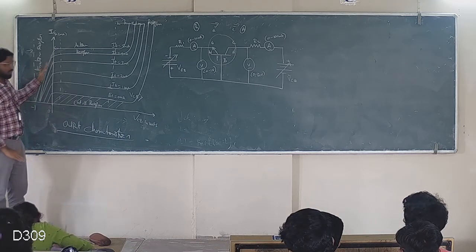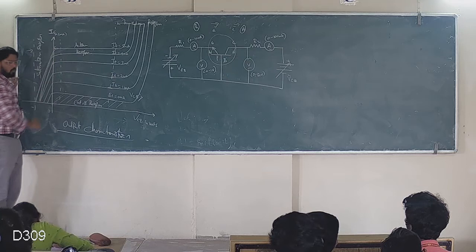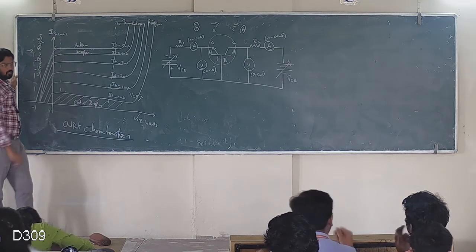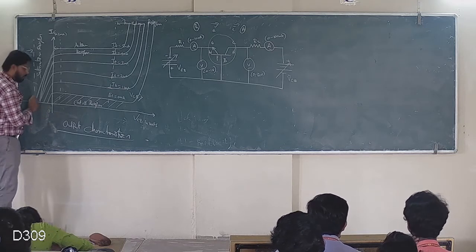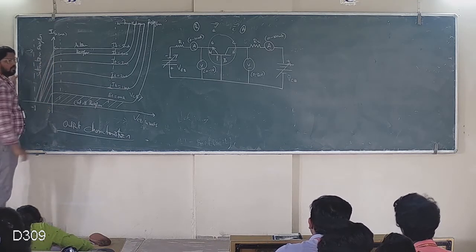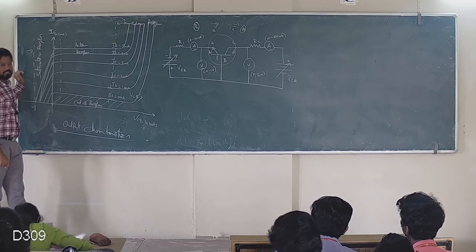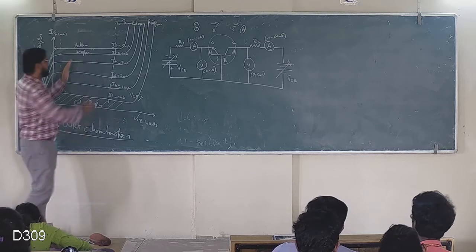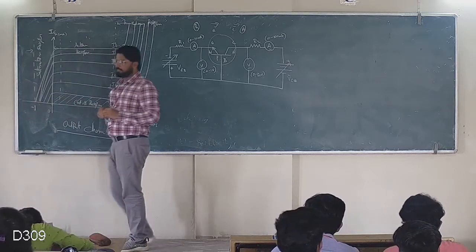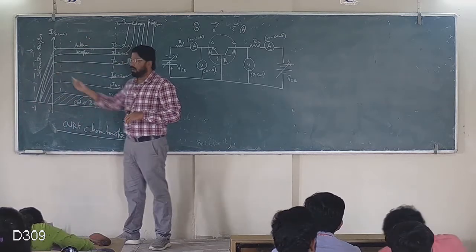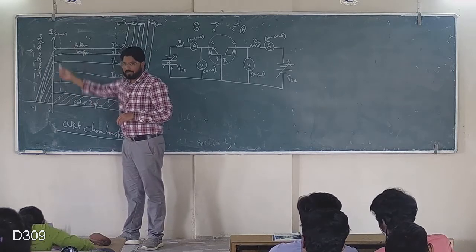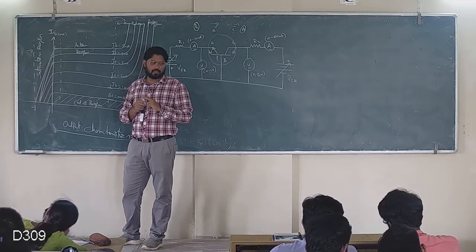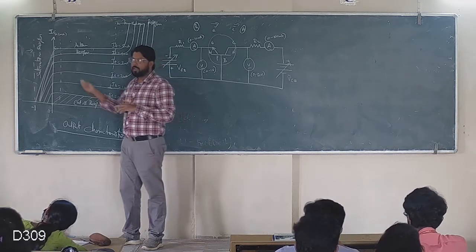And what is this? The y-axis: maximum current. What is the voltage drop? Almost 0 or even less. So this region represents saturated current, or maximum current at the lower voltage. Now what is this? The active region. The active region lies between cutoff and saturation, and only in the active region can your device give a linear response.